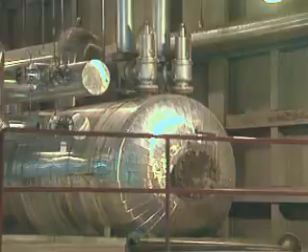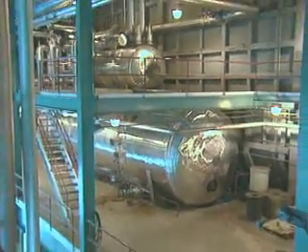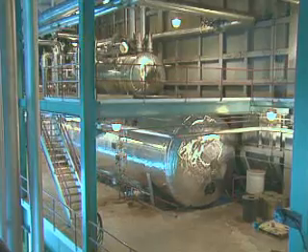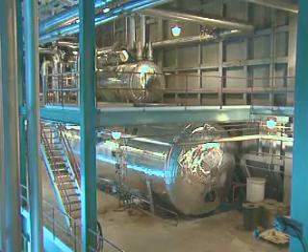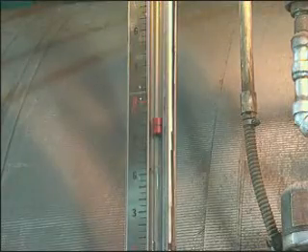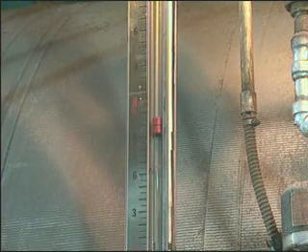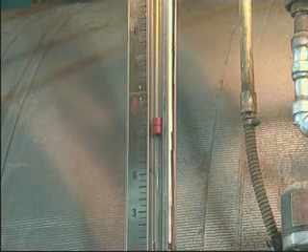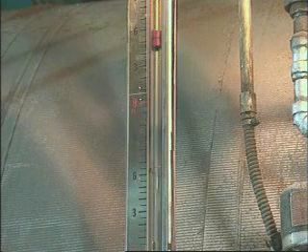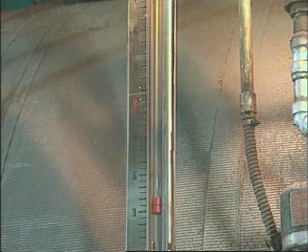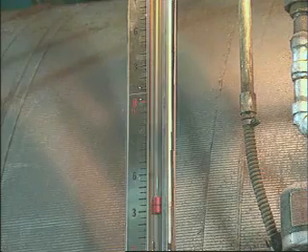The deaerator, which is an open heater, and the hot surge or deaerator storage tank that's associated with the deaerator must also be monitored when a condensate and feedwater system is in operation. Check the level of water in the hot surge tank. There's usually a level sight glass on the tank that's used for this purpose. If the level is too high, water could flow into the deaerator and, in extreme cases, even into the extraction system piping. If the level is too low, the net positive suction head for the pumps downstream of the tank is reduced. As a result, the pumps could be damaged.